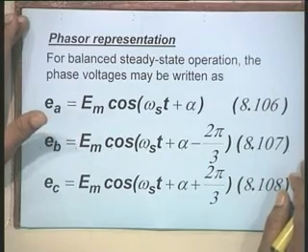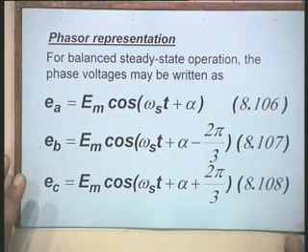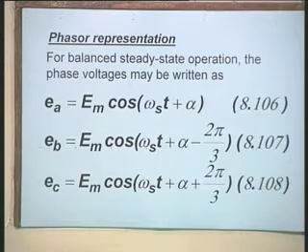Now, we will quickly see the phasor representation. Before we talk about the phasor representation, let us restate some of the facts. Under steady state conditions, the ID and IQ, these two currents, are constant in magnitude. Therefore, basically the currents flowing in the fictitious d axis winding and the fictitious q axis winding are DC currents, direct currents.